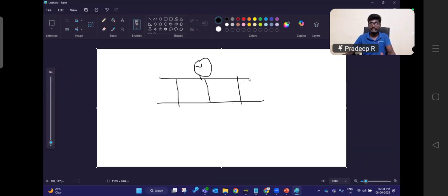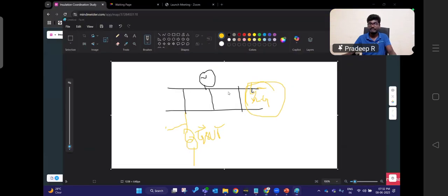Here for the SFO, we can perform studies for the different locations needed as per the client's requirement. Mainly we have to perform all these events on our GIS bus. After that, for example, this bay is connected with my GSUT, the generator step-up transformer. Here also we can do all these events, like an LG fault on the transformer HV side, and previously an LG fault on the GIS bus bar. So depending upon the locations, the number of cases will increase, but by default, these 6 only.